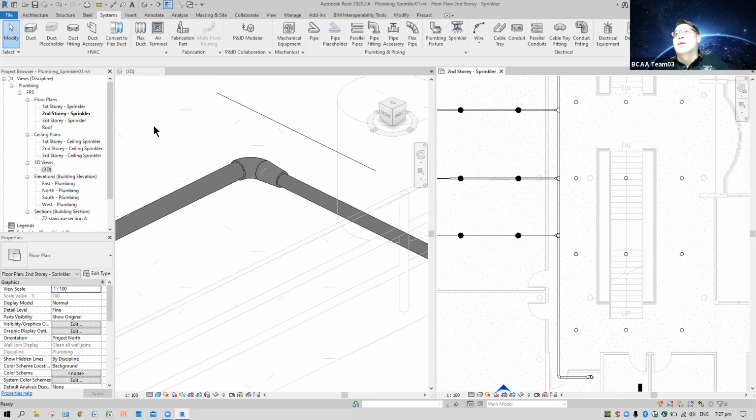Then it's your fault every day because you didn't do your job. Detail they can supply later, unless for some reference purpose, then no choice. If not, it should be complete level by level with all the material set up nicely and then copy paste. If not, it tends to be forgotten. The other method is, never mind, you can change the material at the schedule. At least the update is not so bad. So a schedule, or what we call documentation, is also important in this way. Revit is very powerful in the documentation.